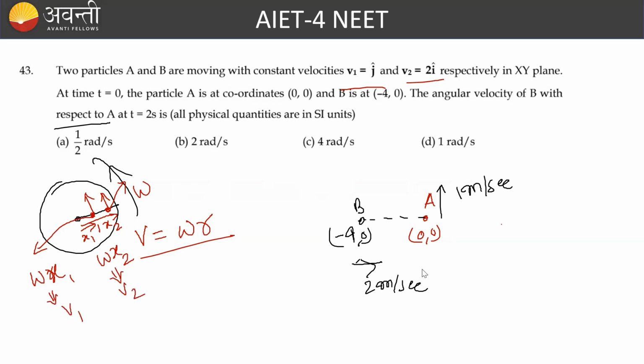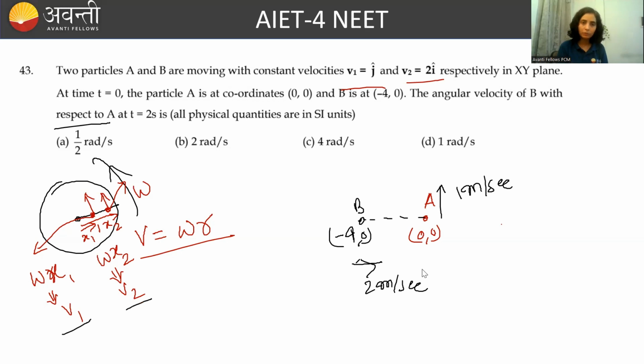Suppose this is given as v1 and this is given as v2. So now just think in the opposite way. Opposite way में सोचने का मतलब क्या है? Now think like you are given velocities of these 2 points. Omega is not given. Velocities are given as v1 and v2. ठीक है. So how you will calculate omega? So you will calculate omega by v2 minus v1 by x2 minus x1. How we are getting that?